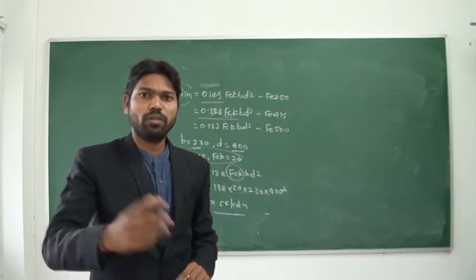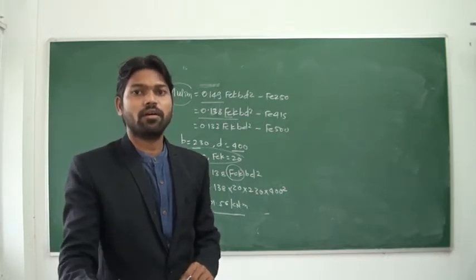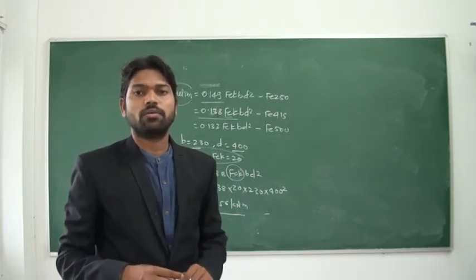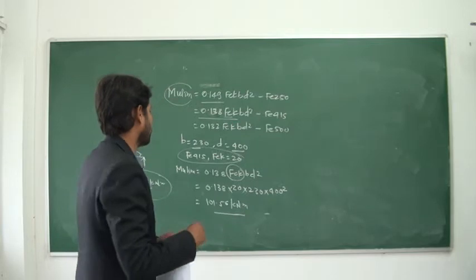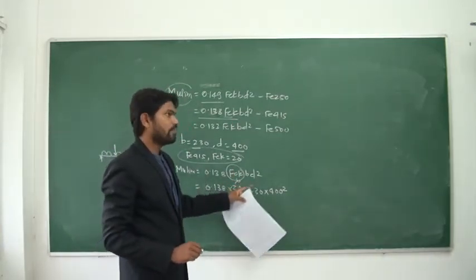So beam as well as slab is casted at the same time. So for one particular beam, if you have to choose a different grade of concrete, it will be very difficult during the execution. So this option will not be a feasible option. Changing the width of beam.